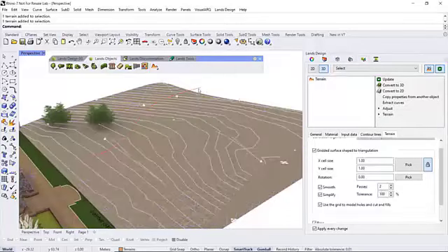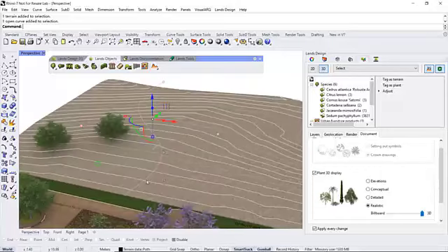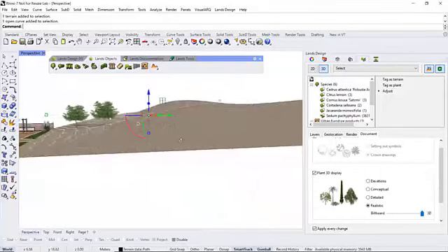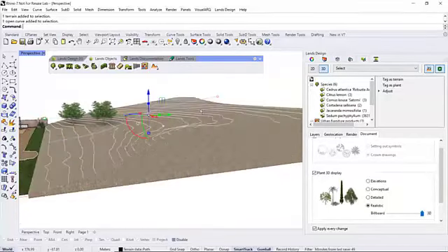For example, I've got this curve over here, and I'm going to use it to add a path on this terrain. So it's important to mention that I've got already this curve elevated into the proper elevation, right? So basically, the terrain will adapt to the position of this curve to produce here some land movement to add a path.